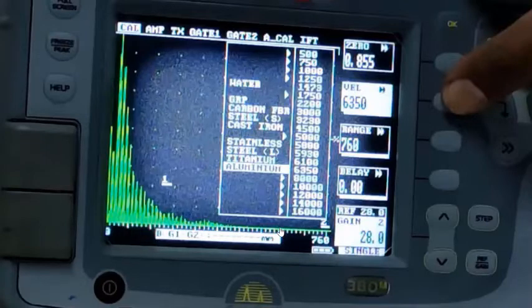Okay, so first we are going to see how the distance is calibrated, because for ultrasonic testing or any other NDT method where the indications or the results are indirect, calibration is very important. So before you do the testing, it is important to calibrate the instrument. That is what we are going to see first, and that will also give you an idea as to how exactly the ultrasonic testing is carried out.